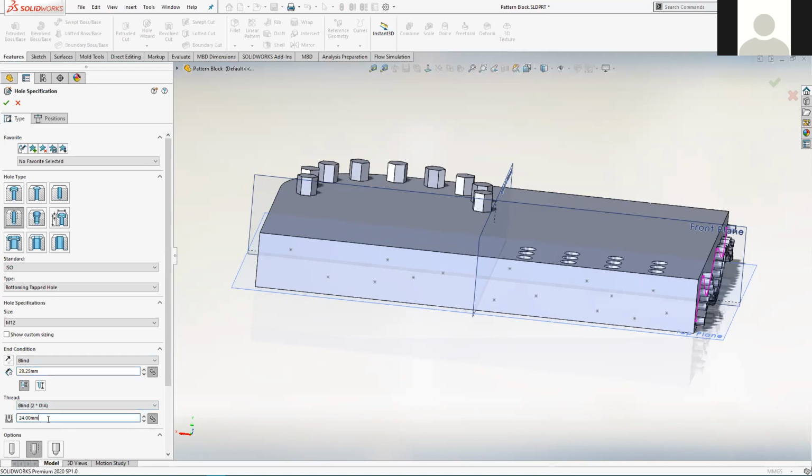And then you've got the depth that the threading tool or the tap will go to when it cuts the thread. So obviously, when you cut the thread, you don't go any deeper than the depth that the hole's just been drilled. So this is kind of a flash forward to when we get into SolidCAM and we're programming some of these drilling operations and tapping operations. So yeah, we'll just accept the default there, but know that they're there. This one's for the thread, tap thread depth, and this one is for the drill operation, essentially.